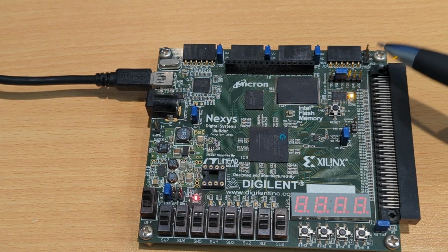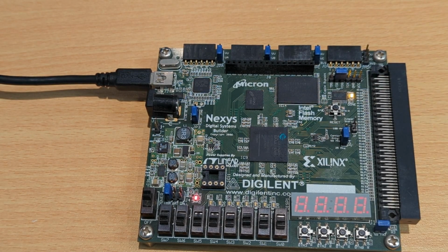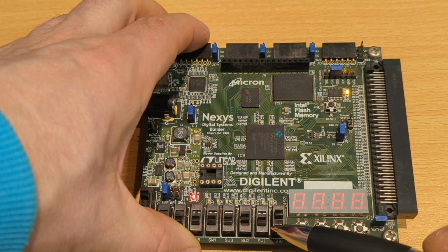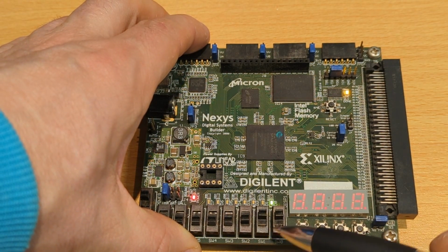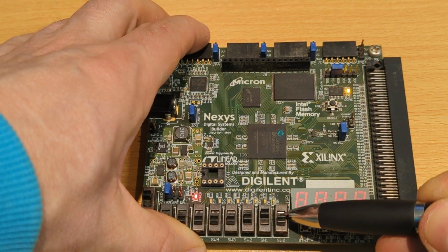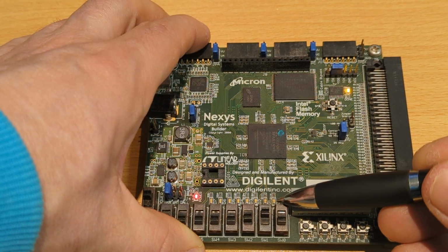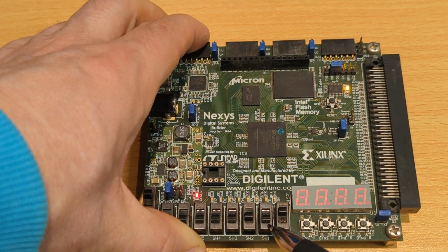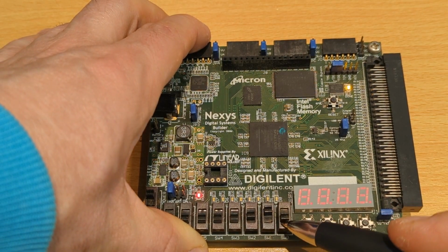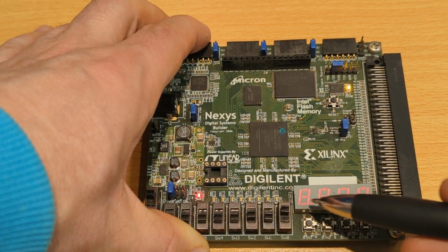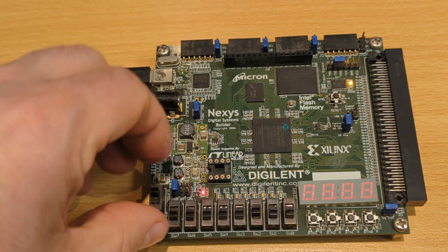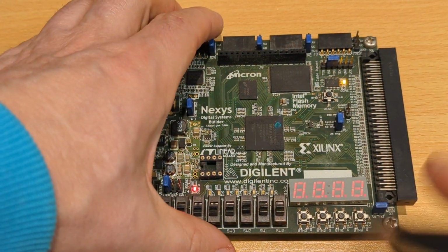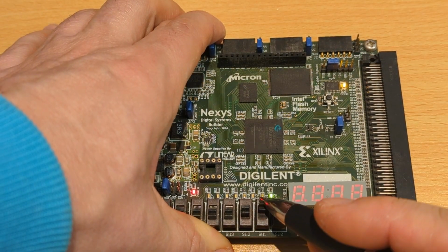says that the FPGA has been successfully loaded from the PROM, and this is the action: SW0 and SW1. These are the switches we programmed so that 1 1 gives 1, and you can see it on the D0 LED, which shows the state of the gate output. So we've got 0 1 1 1 1 0 1 1 and 0 1. Of course it's working as we expected and wanted. When we power it off and on, we still have it programmed, and all the behavior is kept.